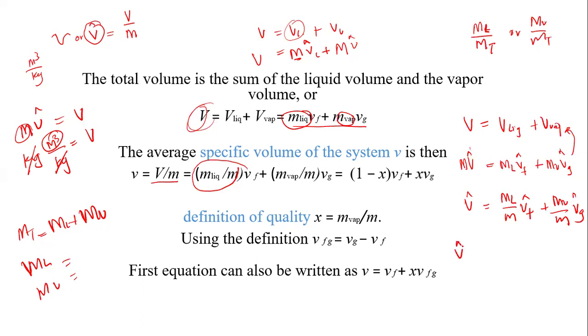And therefore the total specific volume in this case, remember this, it will represent the quality, okay? So the definition of a quality, which is x, is mass of vapor divided by total mass. You understand? Listen to me, mass of a vapor. So that means here I can have, let me show you something. This is the fluid, remember? Mass of a vapor is going to be this side, meaning here we're going to have x vg, right? But you need to understand that for the liquid, here we're going to have 1 minus x.